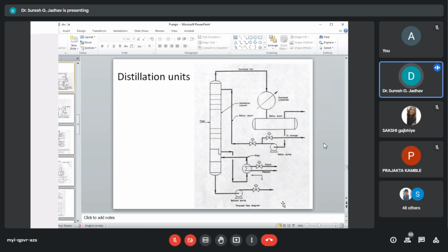The pump normally has a dual service. The pump head requirement should be selected to suit both services. The pump can also have simultaneous operation. All alternatives should be investigated while selecting the reflux pumps.